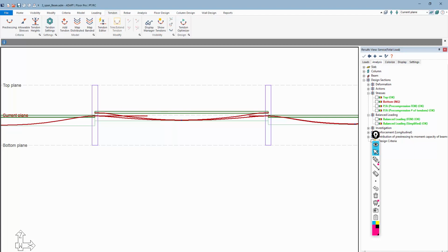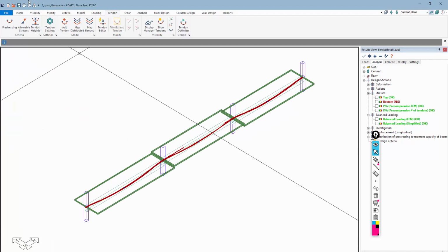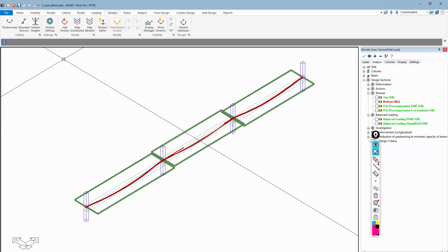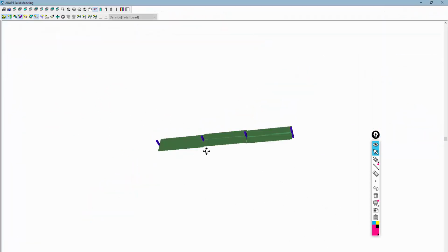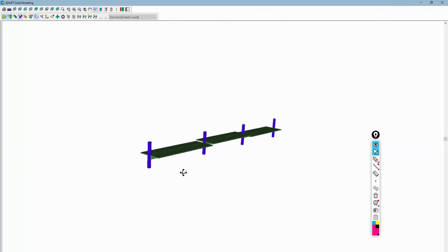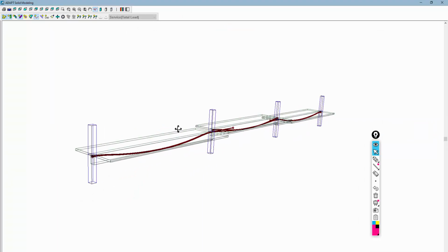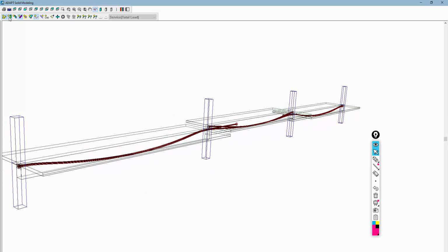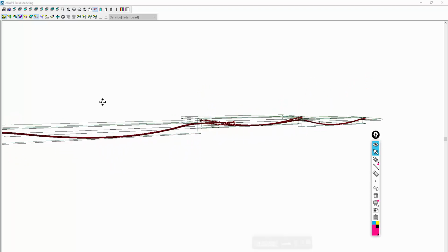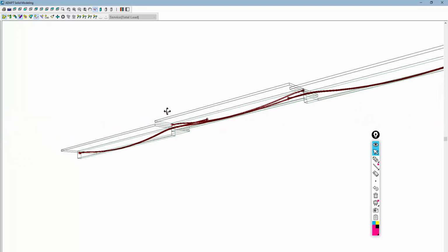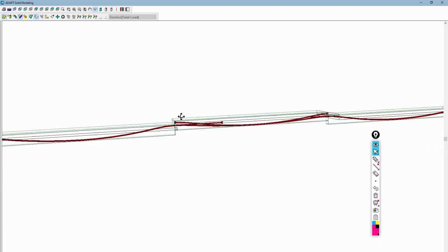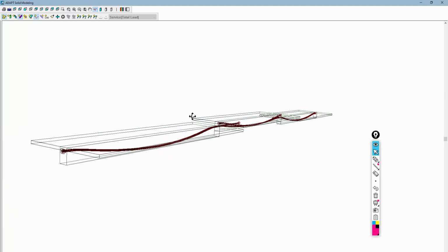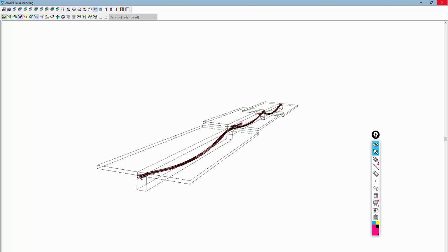Okay, one way to confirm some of the geometry is to use the rendering. So we'll go to the rendering. I'm going to go to a wireframe, and we could turn off the columns. That might be easier to see. And then we can see those tendons in the members. Okay, so this is a nice visual tool that allows you to verify the placement of those tendons.